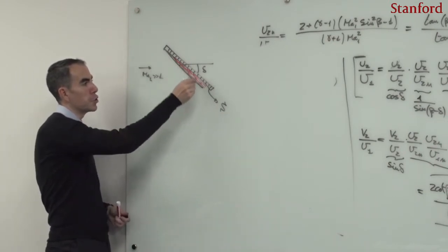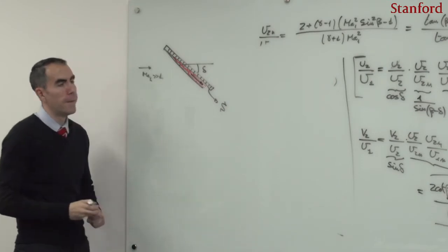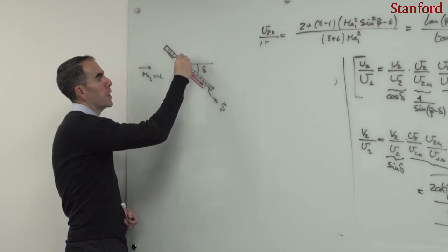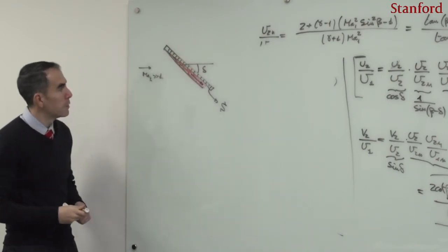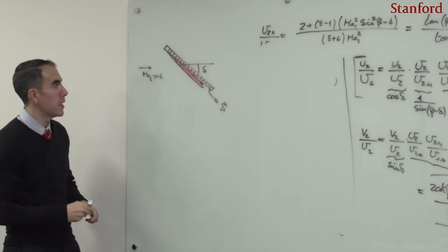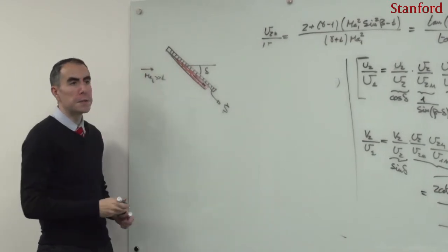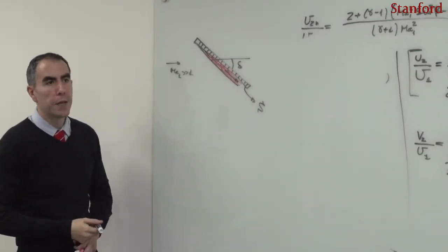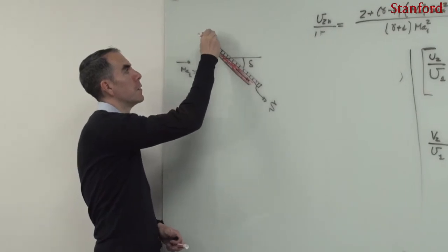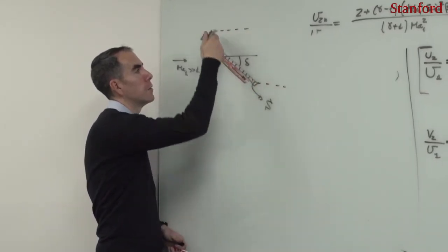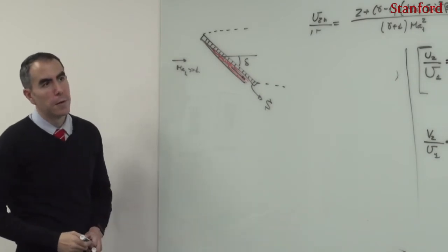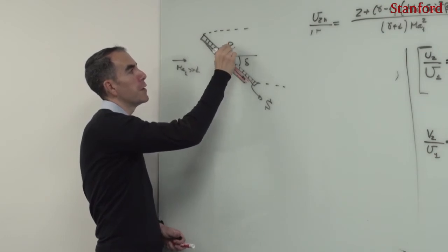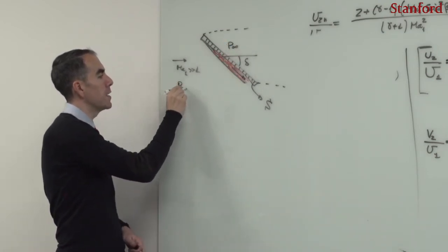And then the gas here in this shock layer is going to get deflected in this direction. Well, so this hypersonic flow is going to generate a force, obviously, on the plate. Before calculating this force, let's just remark that in this theory of Newton, everything that is in the shadow of the incoming stream, for instance, this back surface, the theory assumes that the pressure along that back surface is going to be P infinity, the same as in the free stream.